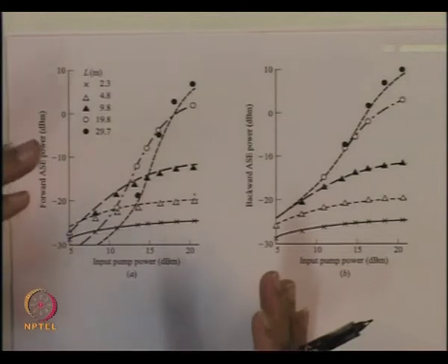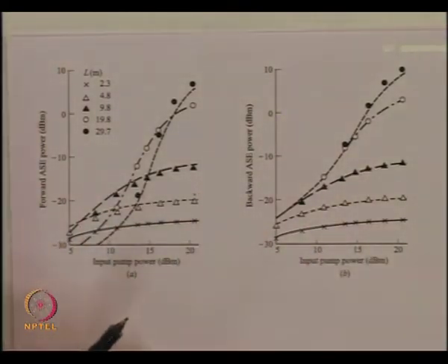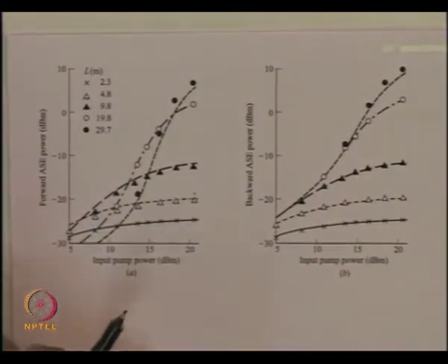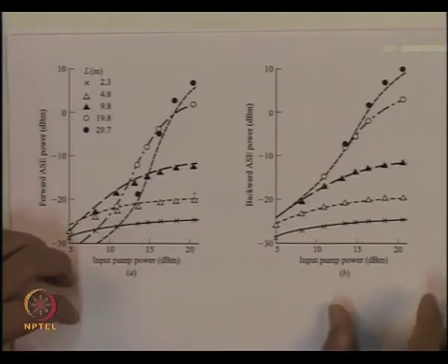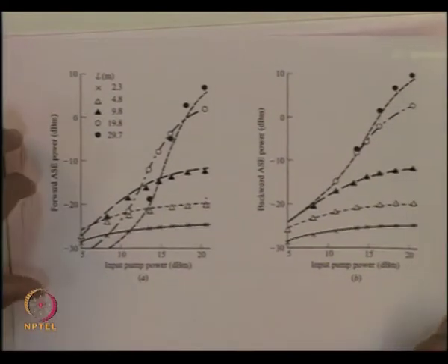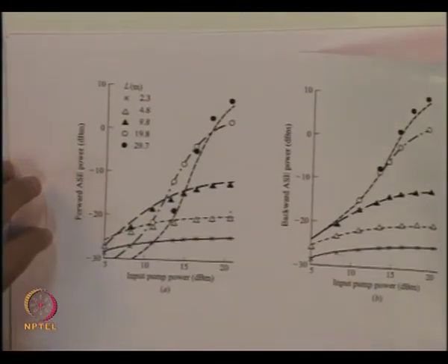So this gives you essentially the relative difference between the ASE which will be created in the forward scheme and the backward scheme. Now what does the ASE do further? When the signal reaches the detector, originally the ASE is a noise, the broadband noise which is generated inside the EDF, and it reaches the detector.